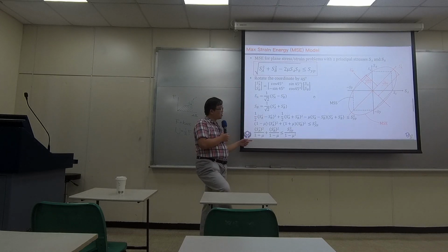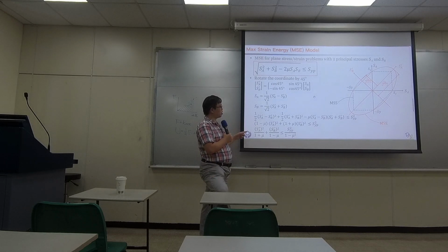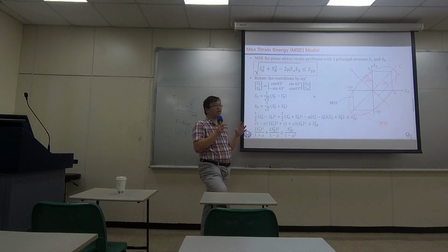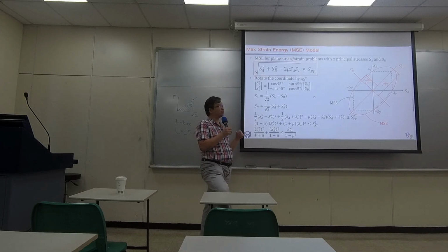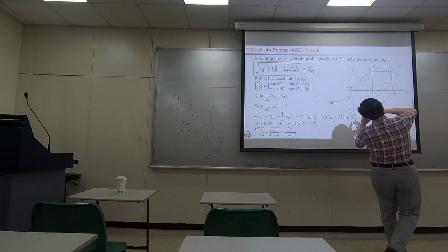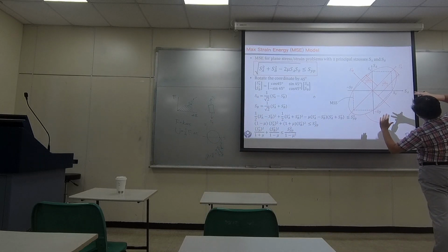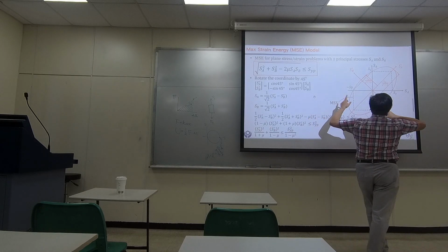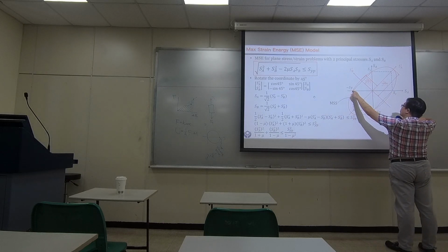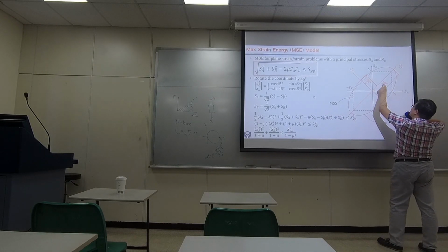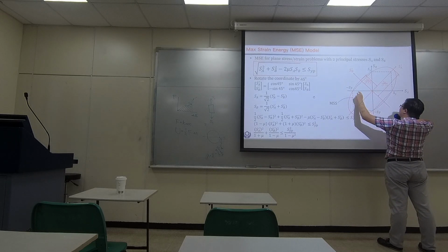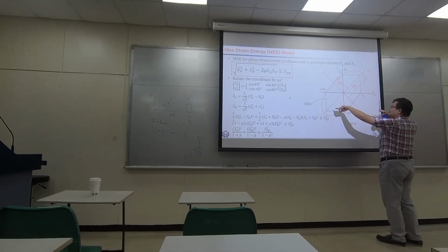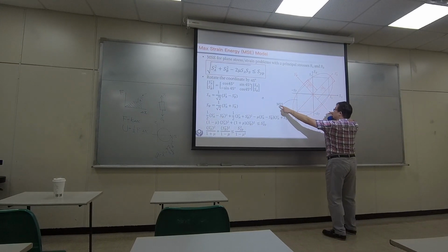At the end, I realized along the SA prime, SB prime coordinate, it's an equation of an ellipse. So it's going to be an ellipse along this SA prime and SB prime coordinate. And if you try to plug in some values, you will realize it's going to pass through these 4 corner points, okay? And it's going to be slightly greater than the 6 dashed lines that we had for the maximum shear stress model.